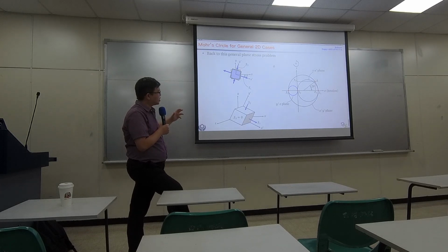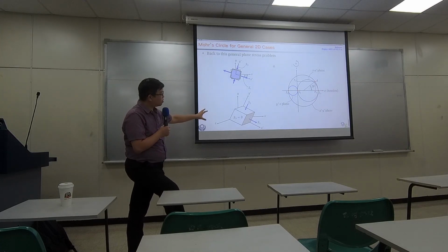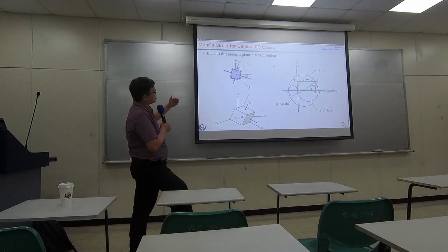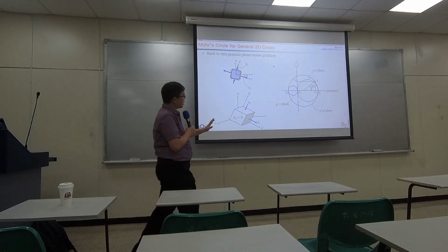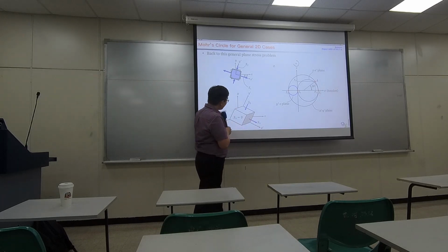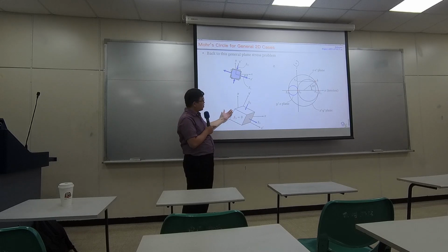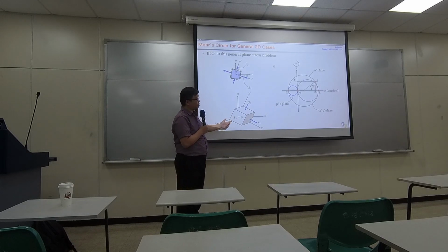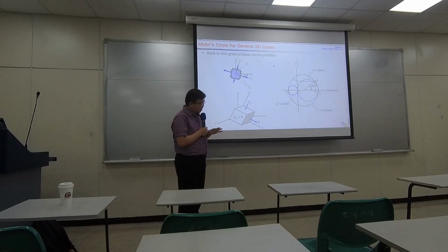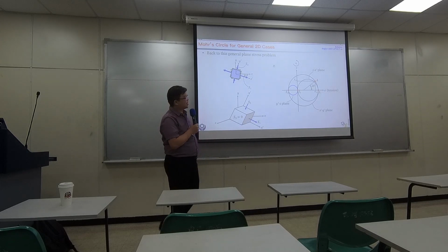When you are dealing with a 3D model but a plane stress problem, we're still working on a plane. However, what's happening is there's no stress along the third direction. So it's like a stress in the plane.